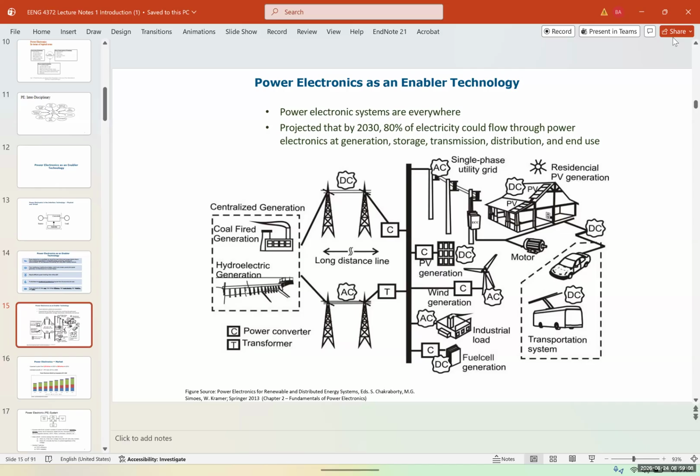The reason is not the chemistry. The chemistry stayed mostly the same. The problem was heat. The mistake that Nissan made with that car was it's an air-cooled battery, not a liquid-cooled battery. And an air-cooled battery, during hot days or when you charge it too fast, gets too hot and is going to degrade. The lifespan of the battery is significantly decreased.